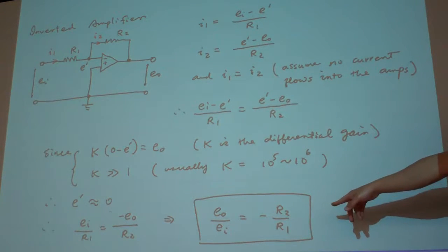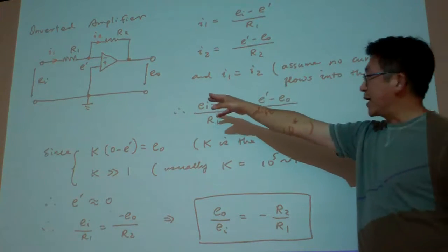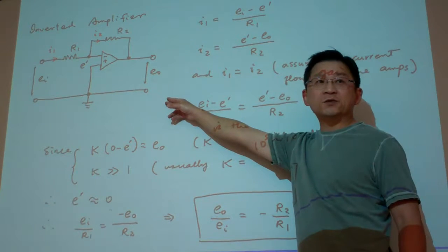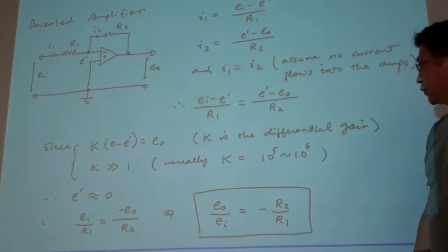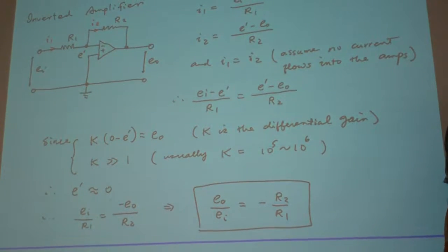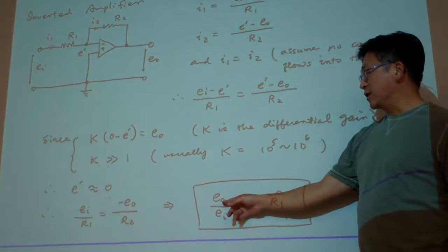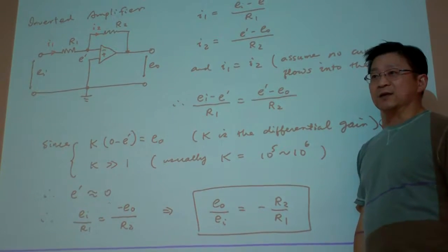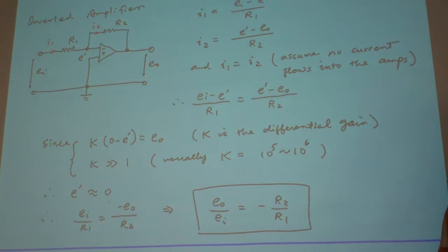And then here, for these operations, for this kind of layout, again, this layout is suggested by a vendor. Okay, this is a very standard, very typical circuit for op-amp applications. So for this one, the output over input will be equal to the ratio of the two resistors. So that gives us a very easy way to say, hey, if I want to amplify the signal, say 2000, I simply take the ratio of the two resistors as 2000, then pretty much I can achieve my work. And the remaining issue is, okay, we can do this one.